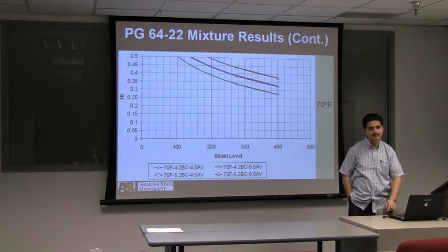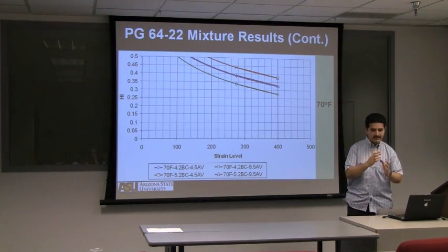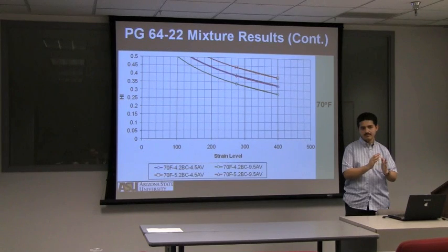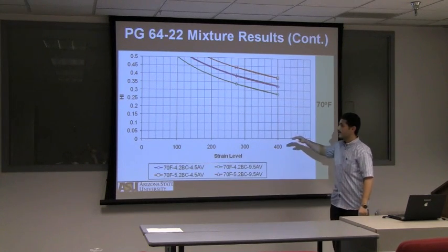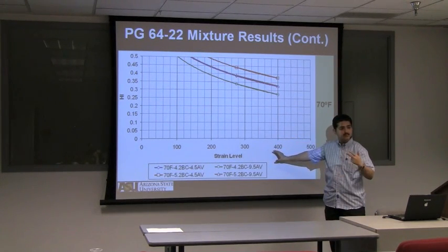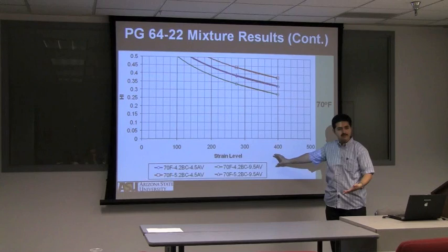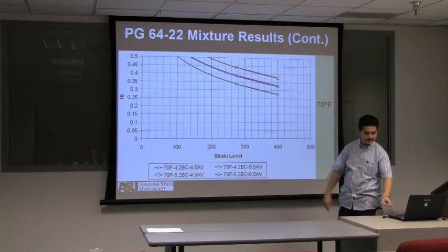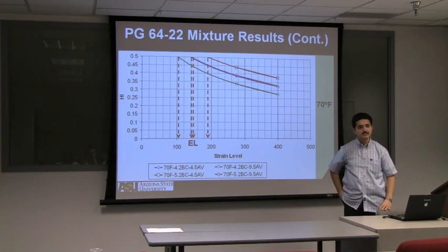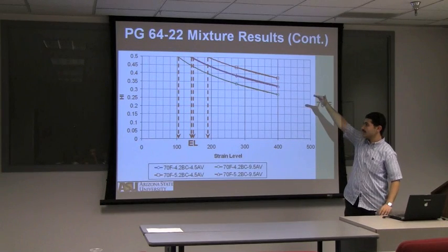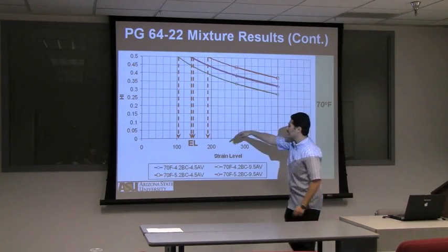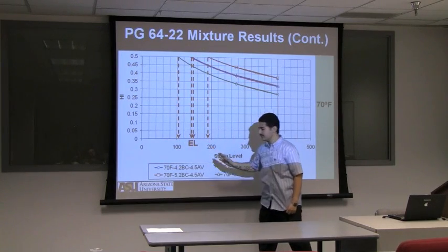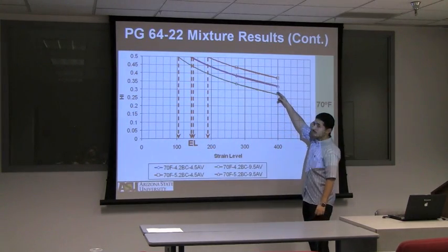The next step, as you recall, after the stiffness ratio, is how to calculate the healing index. Again, I have my model. I run it twice, once with 0 seconds and once with 5 seconds, to plot the healing index, and then the endurance limit will be basically once I reach healing index equal to 0.5. I go down and I select my endurance limit based on different combinations. You can see here I have 4 different lines.